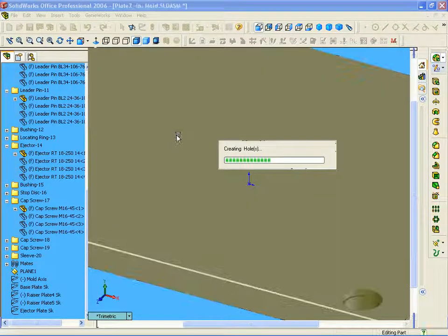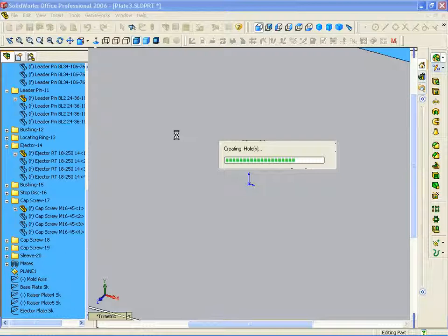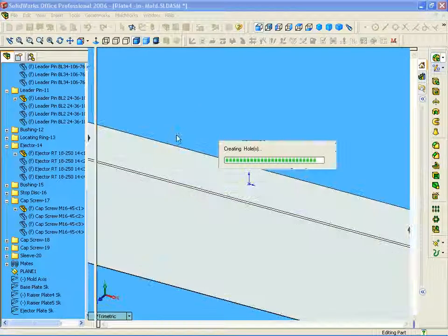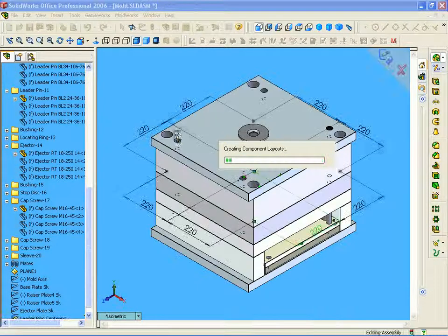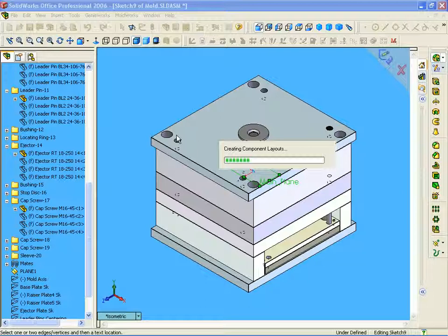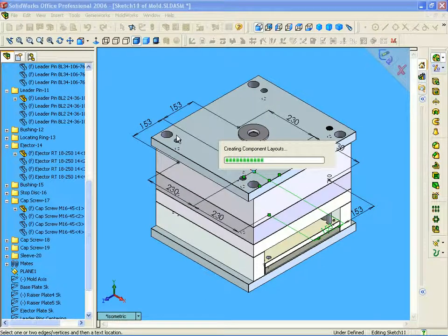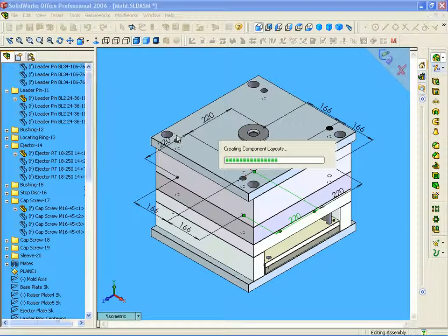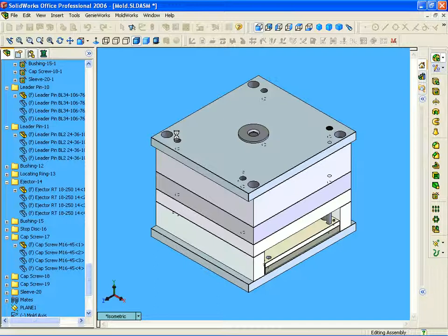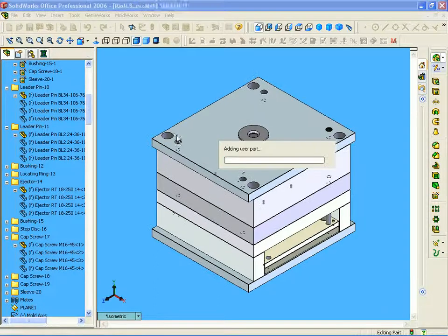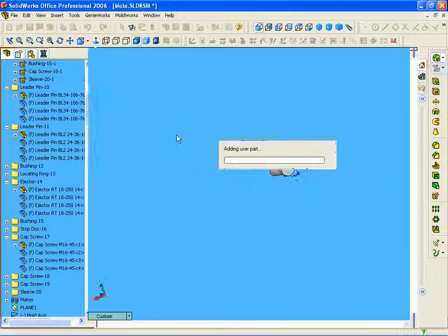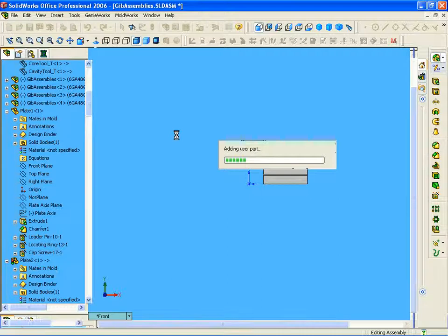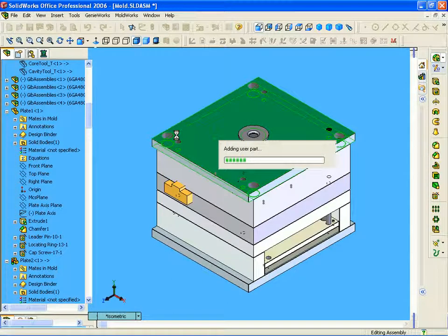Everything is created as standard SOLIDWORKS parts and can be modified or changed by standard SOLIDWORKS tools without damaging the Moldworks data integrity. Finally, we add positioning sketches for the initial components. Since we have already added inserts and slides, their pockets are automatically created as well at the end of the initial mold process.